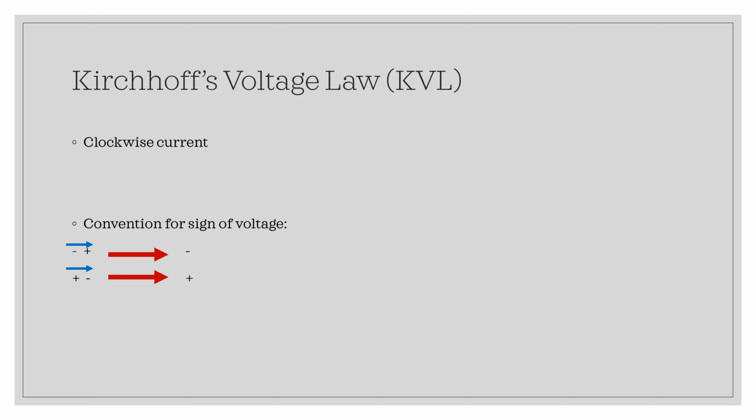So when we apply Kirchhoff's voltage law, when the current is going from minus to plus, we apply a minus sign to our voltage value.